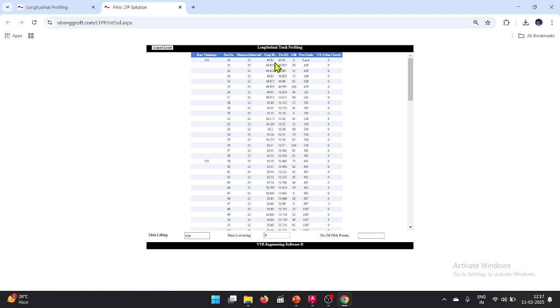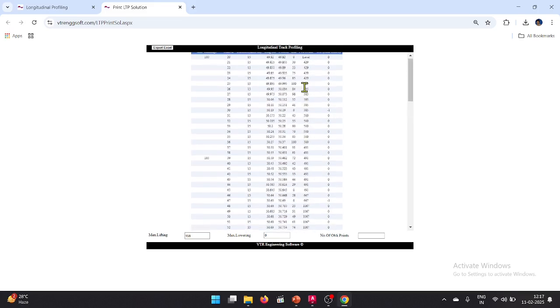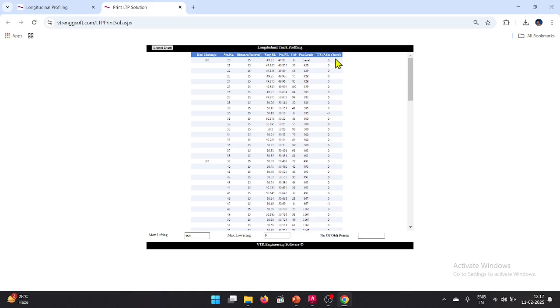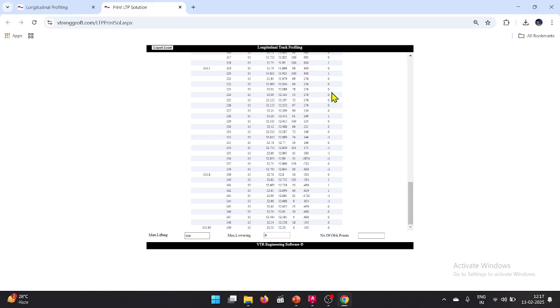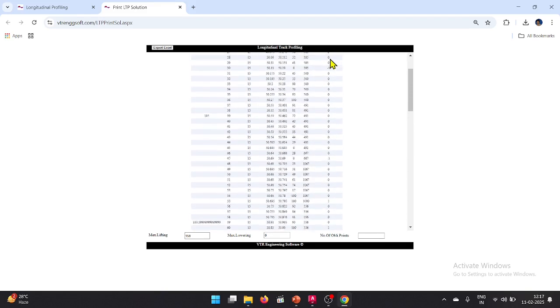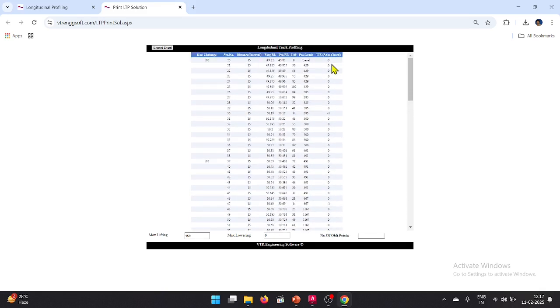What is the existing ORL you have fed, and what is the proposed ORL, and how much lift has to be done, or lift or making up. In case of road, normally we used to make up. And the level difference, the gradient between the two stations, how much we got, like that. Okay. So unevenness, 3.6 meter chord, normally I just put how much the unevenness is. Okay, it will give you the perfectness of the proposed level.